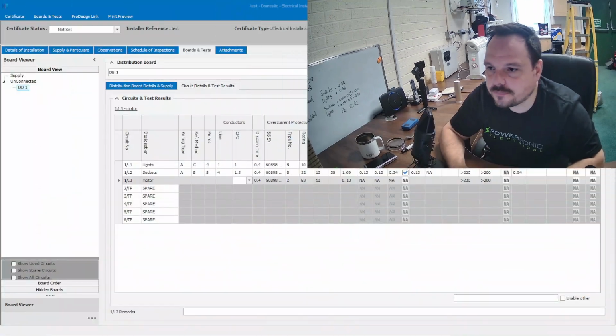And as long as you understand that, you can still get the same verification that all of the conductors have gone back correctly into the distribution board, all of the earths are back in, there's nothing been left in the wrong place, and we've got an acceptable value there recorded.